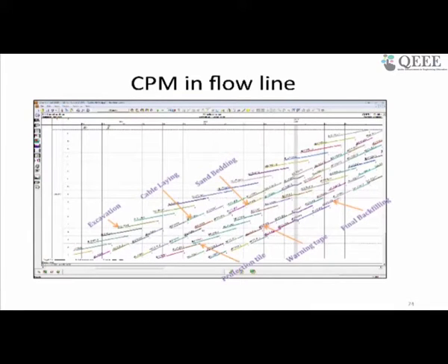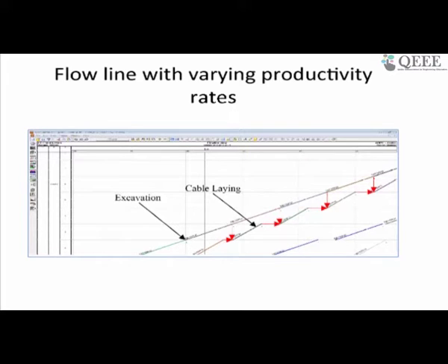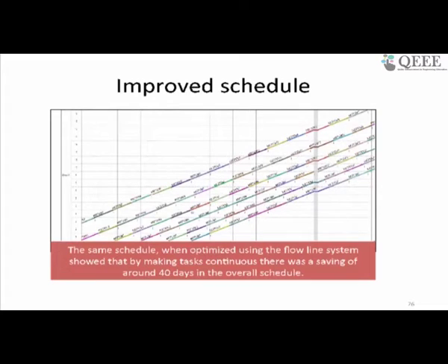When we approached the planning team and asked for their CPM schedule, it looked something like this. There were several errors in the CPM schedule as far as location clashes go. After using LBMS, we were able to streamline the process, and being a linear project, this was more like a production process than a project, because one activity after another happened in a very systematic way.